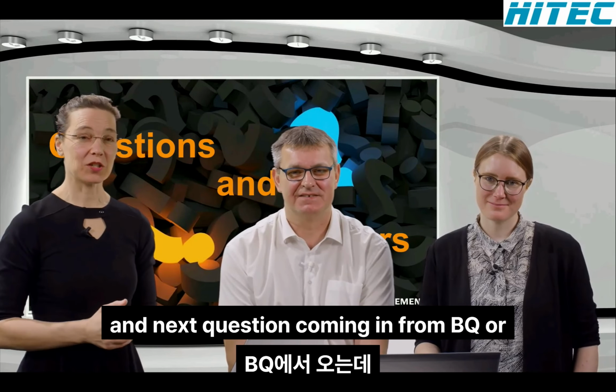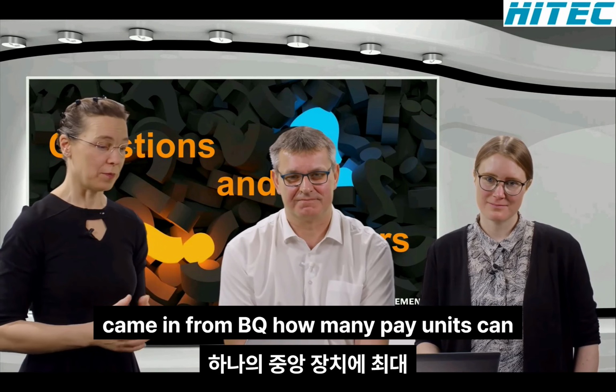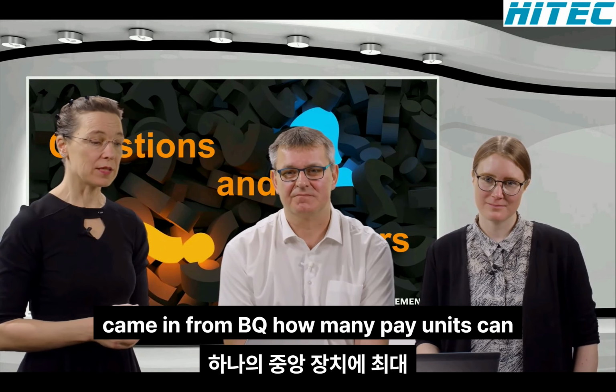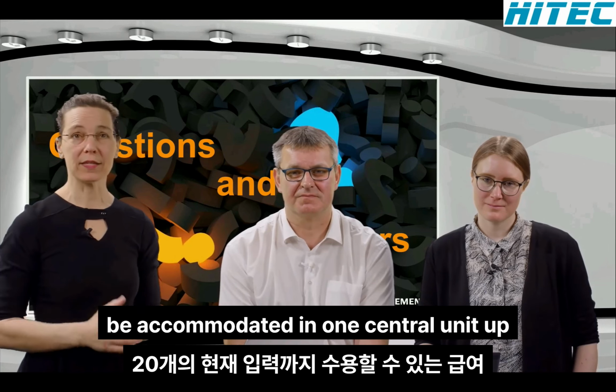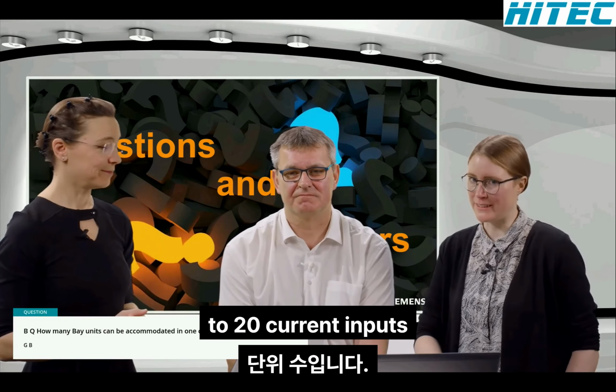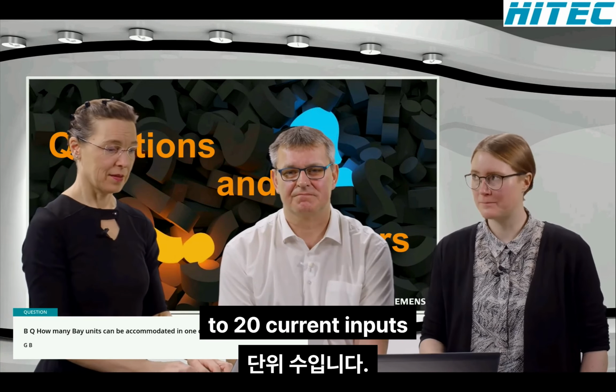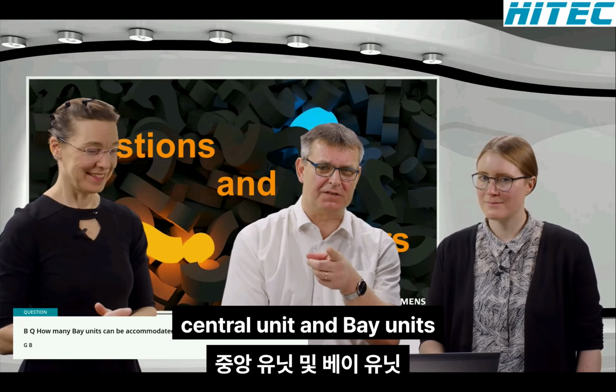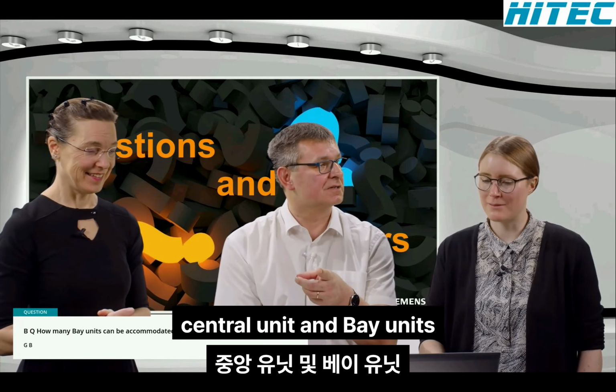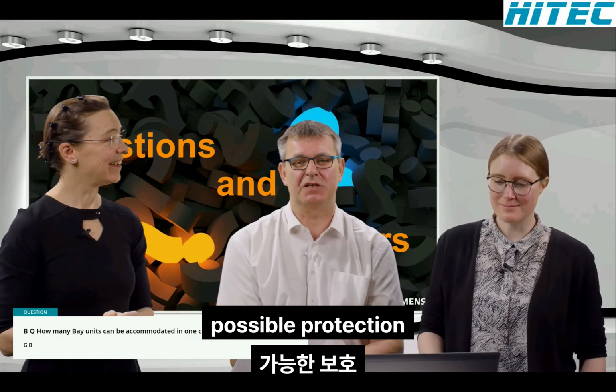And next question came in from BQ. How many bay units can be accommodated in one central unit? Up to 20 current inputs. That was easy. But maybe bay units, I guess I mean bays in one. I'm not 100% sure, because they ask central unit and bay units. If they mean centralized, you have answered bays in centralized busbar protection.